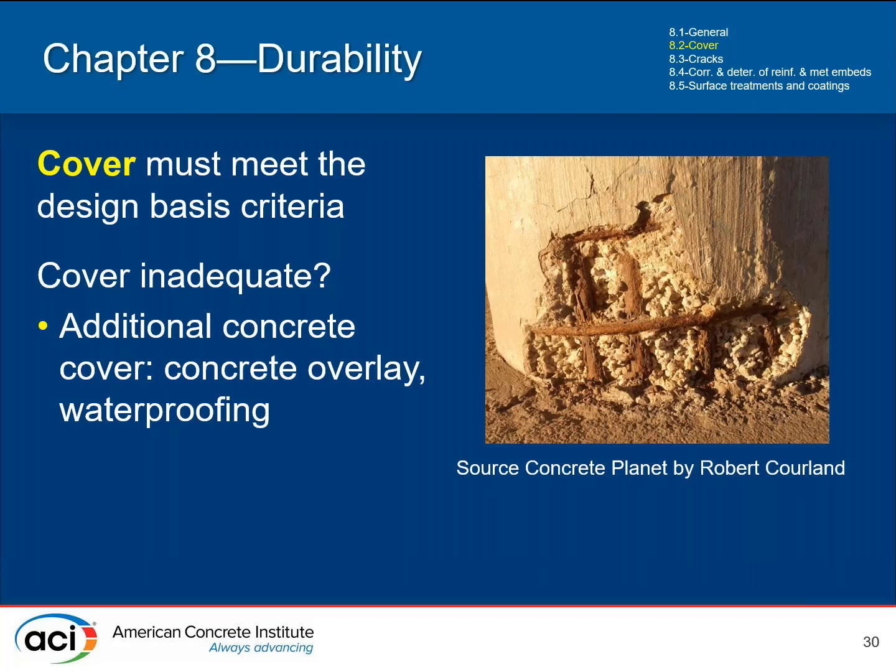Often, though, that's not realistic. You can't say, it wasn't designed for this, let's throw on another 2-inch overlay. Well, now instead of being not durable, it's falling down because you've overloaded. That's not a better situation. And the repair code acknowledges that. It acknowledges that there will be times where it's not structurally feasible. It also acknowledges that there will be times when it's not aesthetically feasible to add cover.